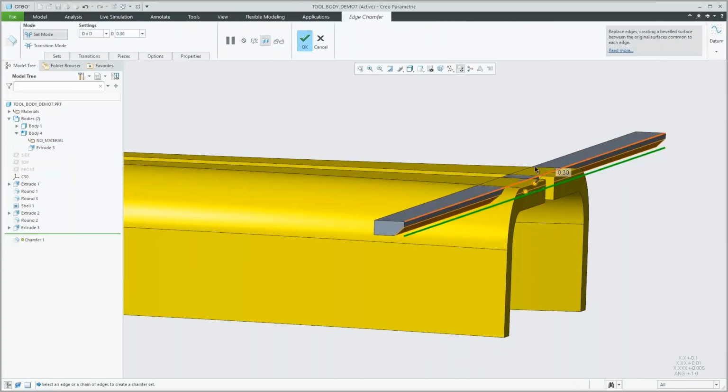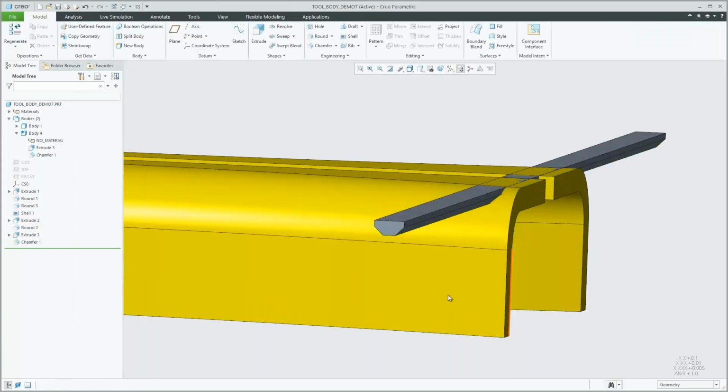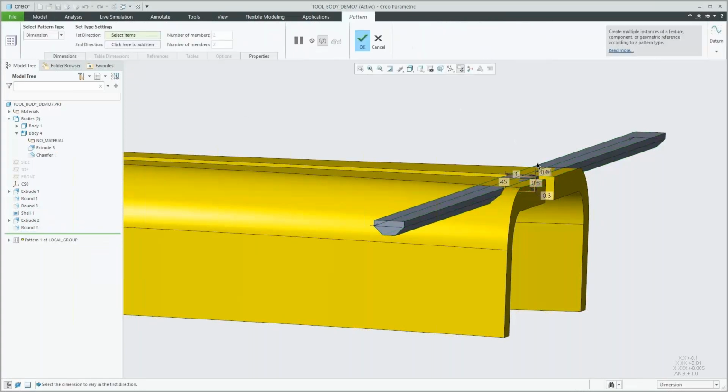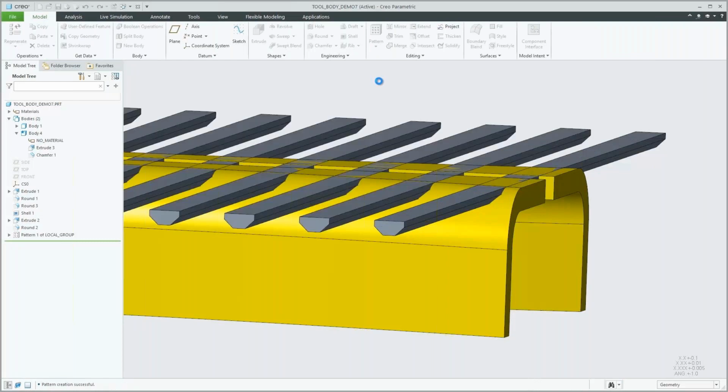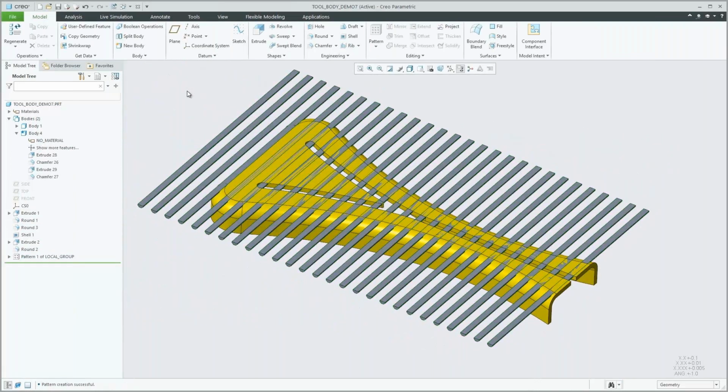And now that it's a separate entity, you can get it to the way you want, chamfer the edges, right? If this was a surface, you couldn't just chamfer those edges. So that makes it way easier to work with. And then define how many you want, so pattern it out. If you want 27, great. And this will go match past.